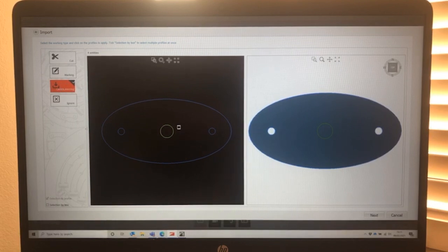So again, if for example this component, this hole in the center here, wasn't a hole, it was a position that you wanted to drill out afterwards, because in say 20mm material, the general 2D rule applies, so you wouldn't be able to put a very small hole through the 20mm thick plate using a plasma system.